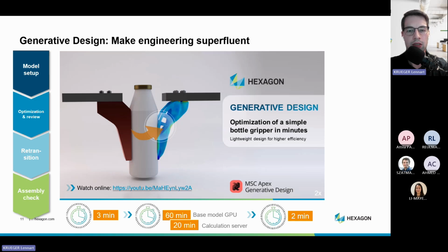This video is a little bit older. There we had to really switch the software. Nowadays you can just do it with one click, the option to switch the mission from generative design to Nastran, and then you have your part in the graphical user interface for the Nastran reanalysis. Here you can remesh it with a tetrahedral element. Then you can check your element quality like Alex did, and your loads are already attached to it.